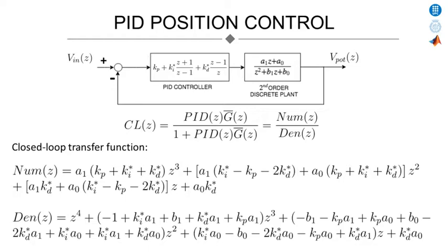Two main problems were identified when closing the closed-loop system. On one hand, we have 4 poles to fix by 3 parameters. This means one of the poles was freely fixed and we had to check whether this pole was stable and not dominant. On the other hand, we obtain 3 zeros, which affect the dynamics of the closed-loop system. So, let's see how to improve this controller in order to delete those effects.